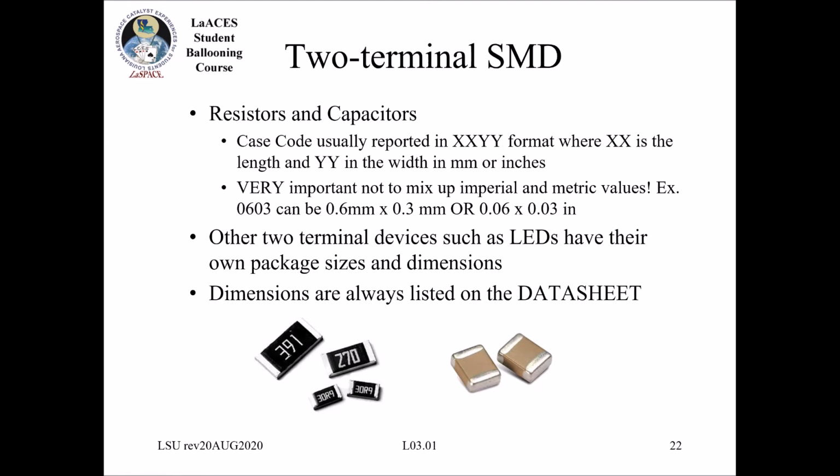Now that little board that I showed you earlier had 0603 components on it. It's very small. And I got an external board manufacturer to solder all of those components. I did not do that myself. In fact, the image sensor has pads on the bottom of the image sensor, so I cannot do it. You have to do it with a special machine that does that kind of soldering. But in this class, we're going to want to use things that we can all solder ourselves, either through-hole or larger size surface mount components.